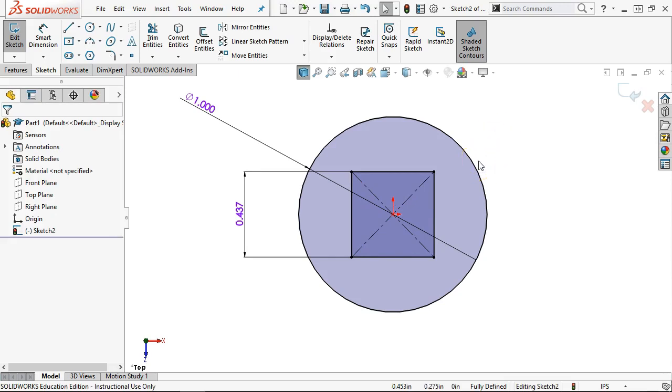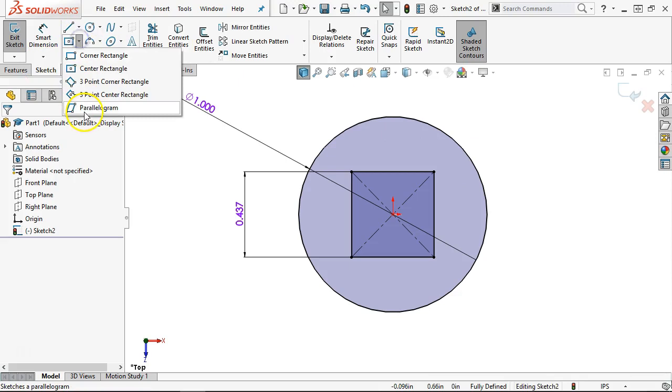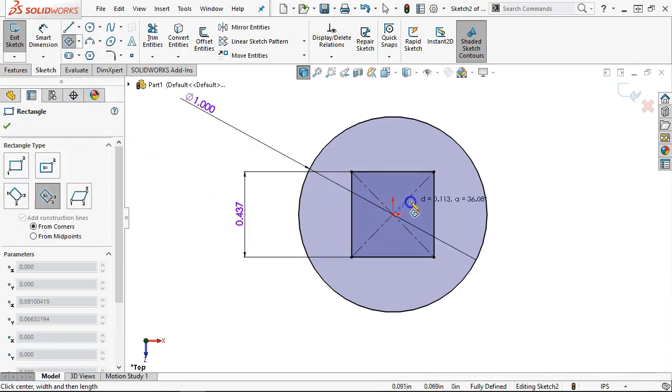All right, so because we're given a 1/2 inch across the flats, do we go ahead with the contour and region, or do I try to set a chamfer? All right, we could set a chamfer at 45 degrees, but there is also such a thing as a 3-point center rectangle that when I drag off in, well, let's make it a little bit longer.